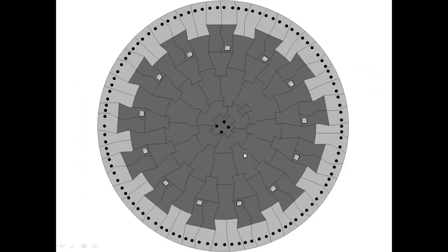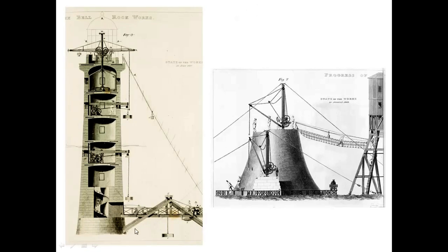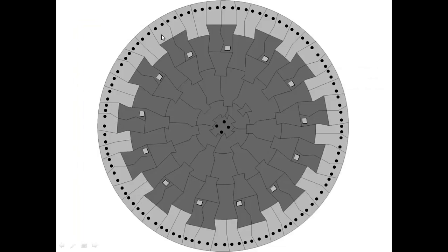But the other thing they did to resist wave impact, now this is a cross section through the foundations. So these are stones. So down at this level here, it's a continuous stone circle, isn't it, and then it starts to break up as you go up through the structure. So they cut the stones a bit like a jigsaw, as you can see, to interlock with each other, so any wave impact would be resisted by this astonishingly beautiful array of stone.